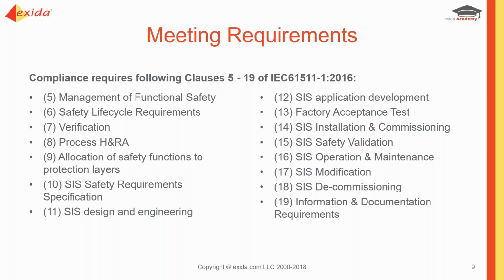Clause 12, the application development. If we're going to be using a safety instrumented system with logic solvers, how are we going to program those? So application development is very important. What languages are we going to be applying? Clause 13 talks about a factory acceptance test. This is where we would bring the application software together with the logic solver for the first time.